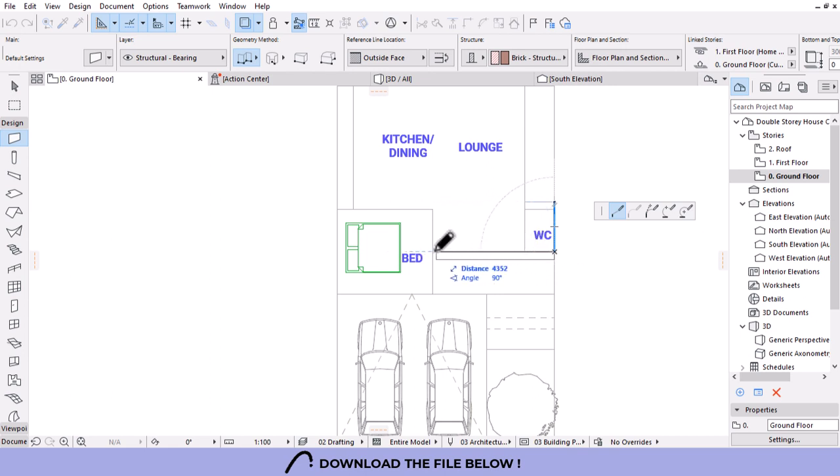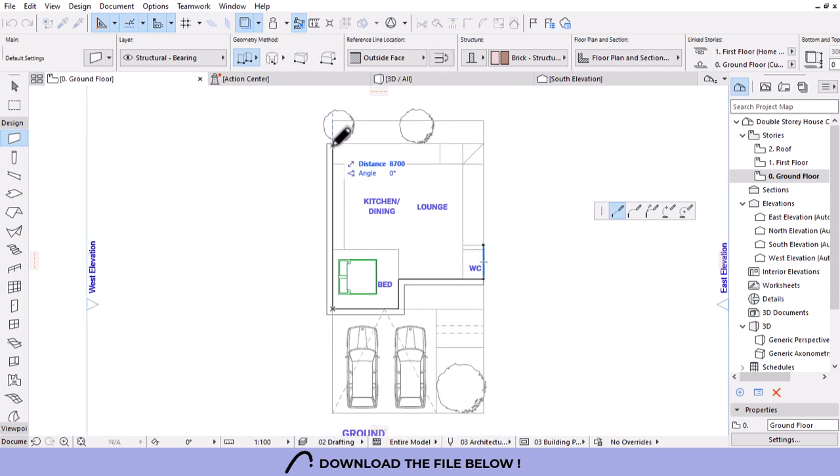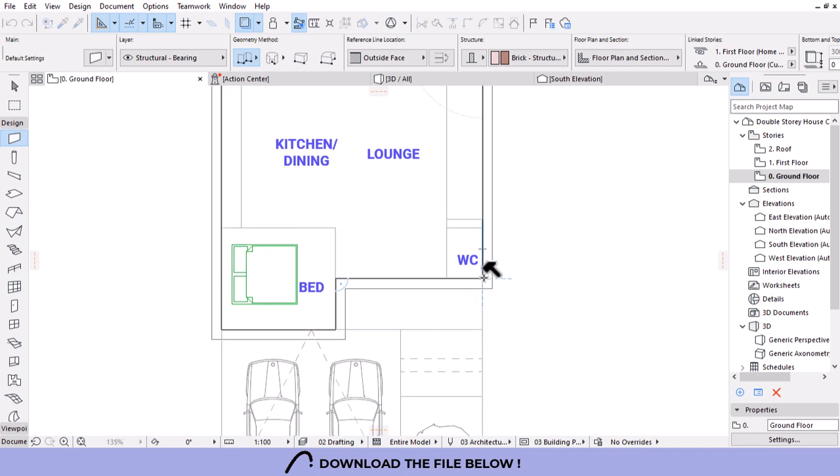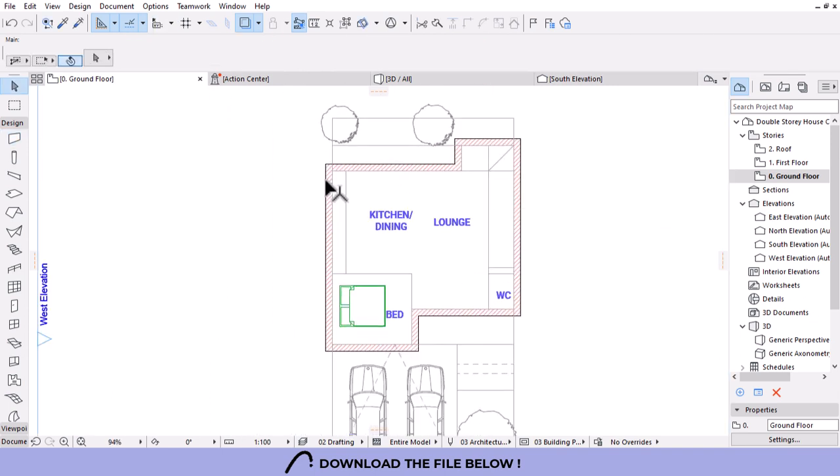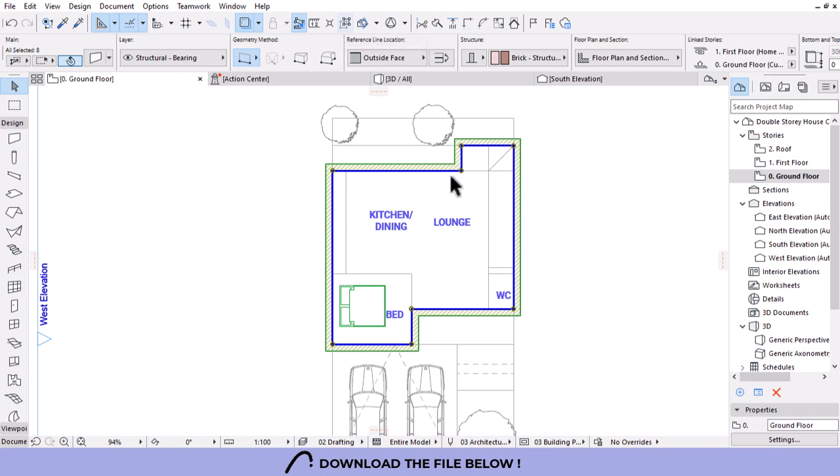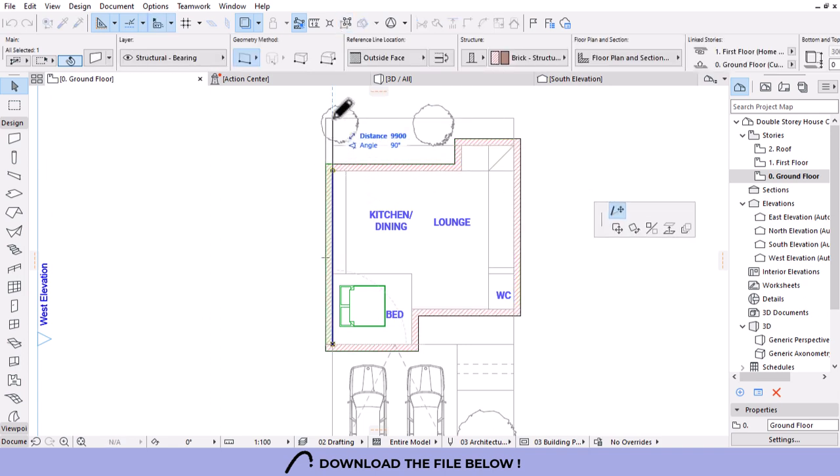So the reference line is going to be on the outside, or on the left, which is fine. Then I'll go just that. Let's go to this wall, then here, there we go, and then that's it, and we can close off like that. Perfect. So by default, it groups all the walls because I was using a chained or polyline method. But if you want to edit and access a single or individual walls, you have to unsuspend groups. So I'll unsuspend groups and then click here to stretch this wall to there.